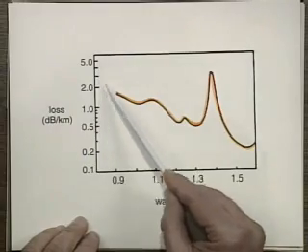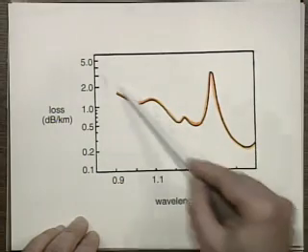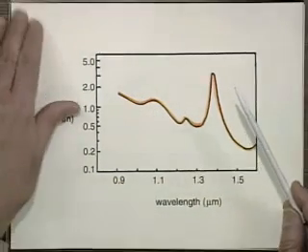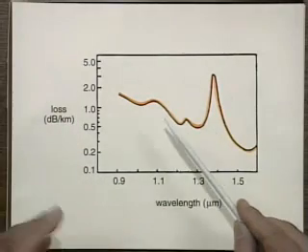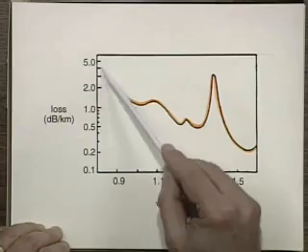And the reason why it's small is, first of all, because the total internal reflection is really 100%. All right? There is no loss because of that. And the reason there's any loss at all is because you're squeezed in from one side. On this side, you have what we call Rayleigh scattering. I don't want to get into it right now, but you get scattering from density fluctuations within the glass.